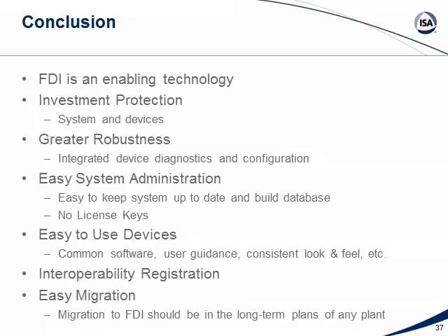When you get a new FDI package for that device, through your management of change procedures, and you get it updated, it's not installing new software. It's not double-clicking and running a setup. It's literally just throwing a file into a directory, the system imports it, and you get a nice little catalog. Easy copy deployment, as we call it. And again, no explicit license keys or anything. FDI is really focused on providing all the functionality without the extra costs.